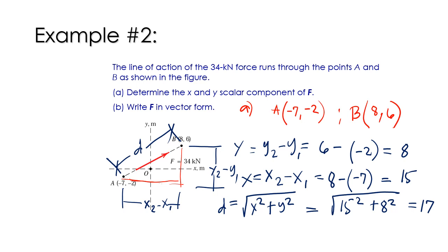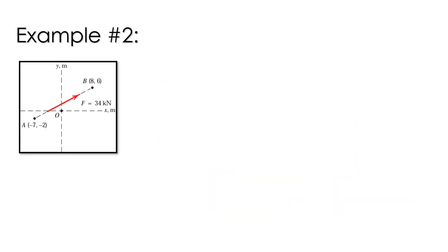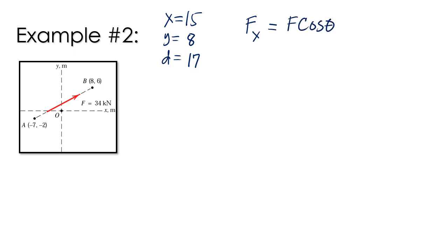So in order to determine the scalar components of force F, in the next slide, since our x is equal to 15, our y is equal to 8, then our D is equal to 17. So our Fx is equal to F cosine of theta.